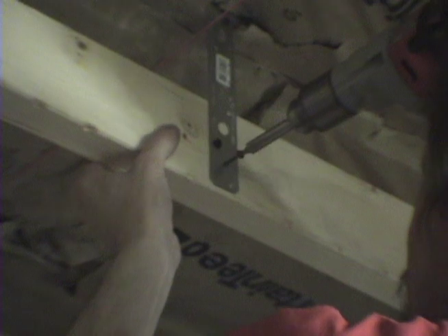We used a strong tie perpendicular hanger for this job, which allowed us to build the ceiling in place. An alternative would be to build the ceiling on the floor and then raise the whole ceiling into place. I thought that might be a pain, so I opted for this easier solution. You just attach the hanger to the support beam, then place the cross 2x4 in the hanger and screw it into place on the sides. Then attach it to the hangers on the other end. Double check your level as you go.